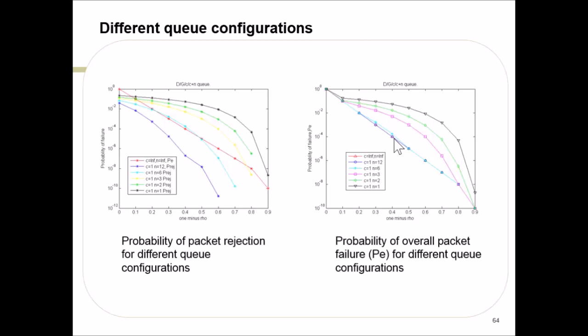Yeah, you can think of it this way: in layered decoding, we are operating on the entire code word, but let's say you have 1,000 check node equations. What I'm doing is I'm not updating all those 1,000 check node equations. I'm only updating 100 of them. And then you update all those 1,000 bits. And wherever those 100 lie, you're putting them into the next 100.